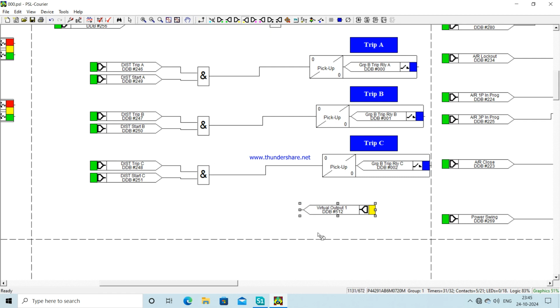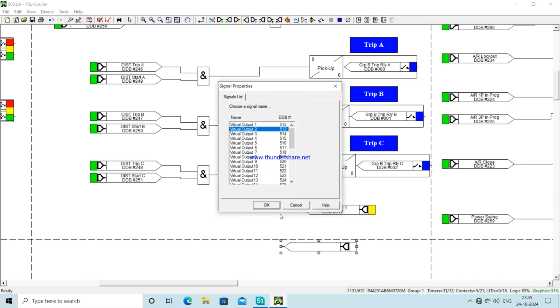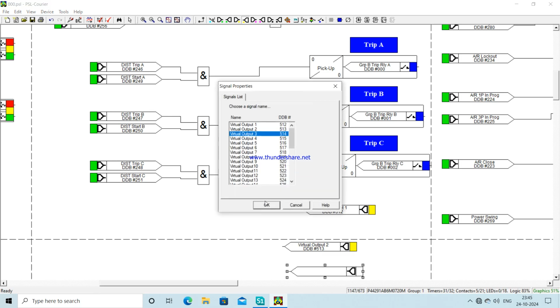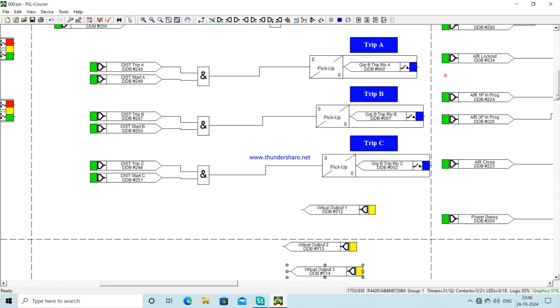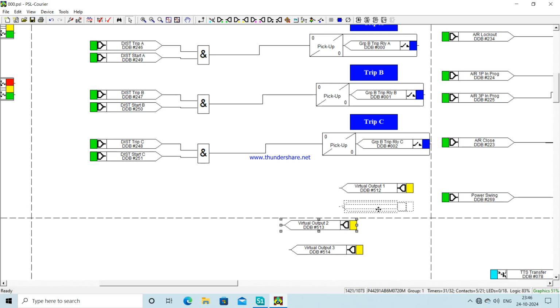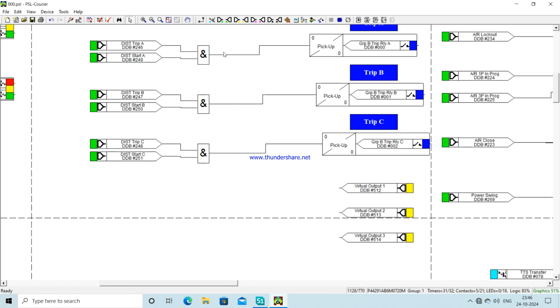In that case, only a single pole will trip, and then with the auto reclose signal it will get reclosed. So 3 single phase trippings for the 3 phases will be designed through 3 virtual outputs or GOOSE output signals, 1 three-phase tripping and 1 auto reclose output.